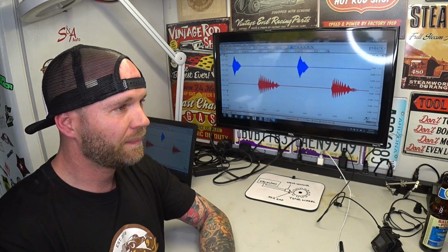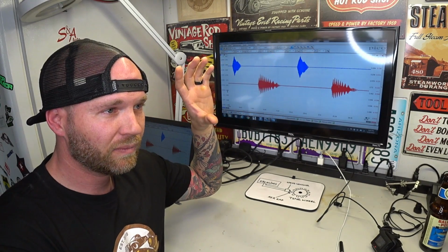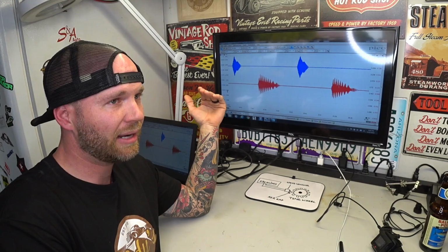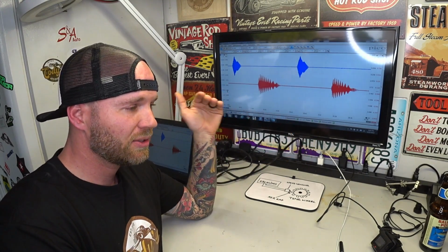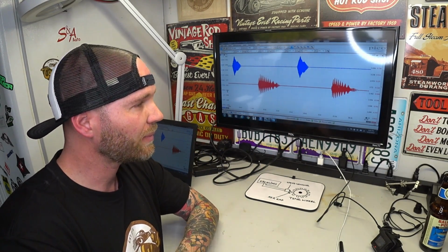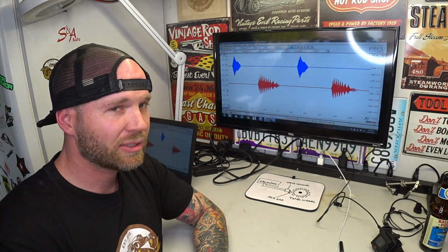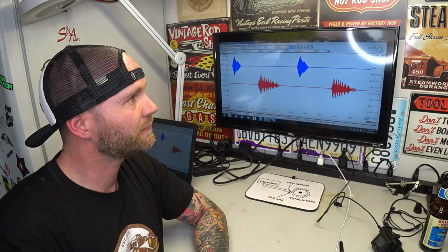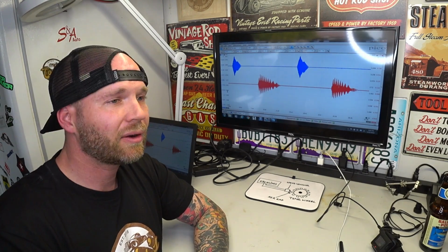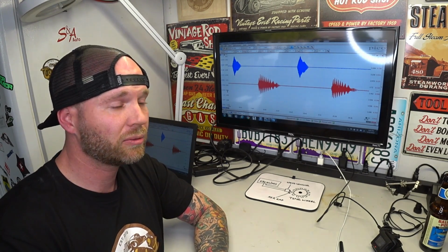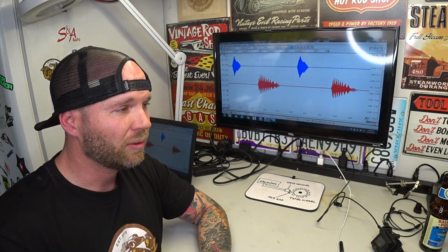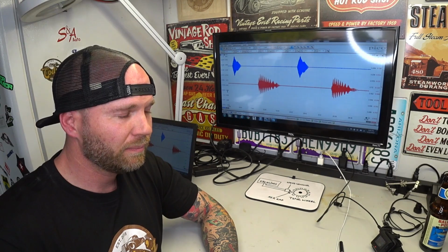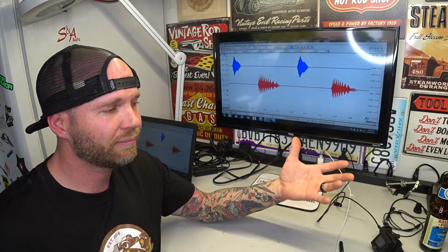So front door is, you go to the front door, you're seeing exactly what's getting input to that control module. And backdoor information is just that. There are times that the control module, any control module for that matter, will either misinterpret the information or they're outputting a different kind of signal.